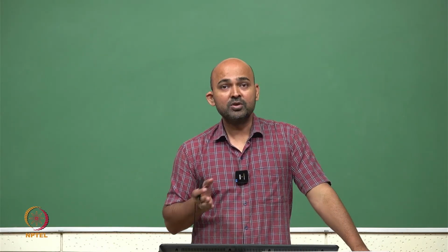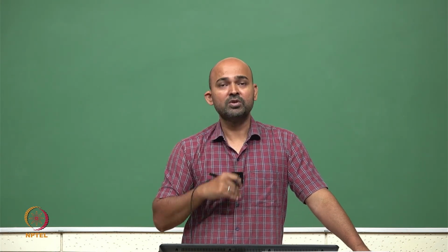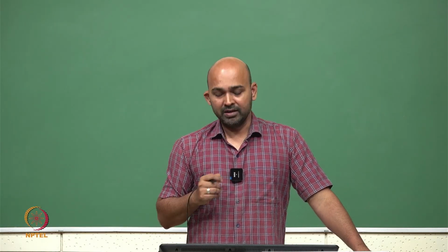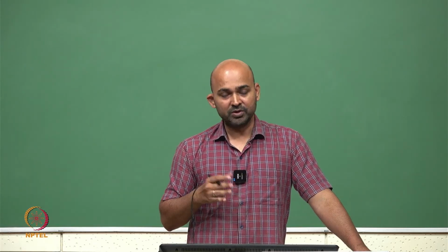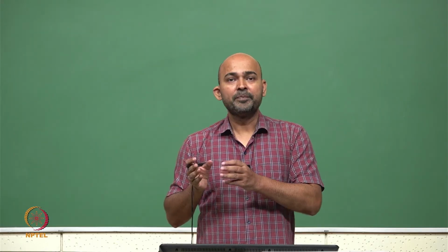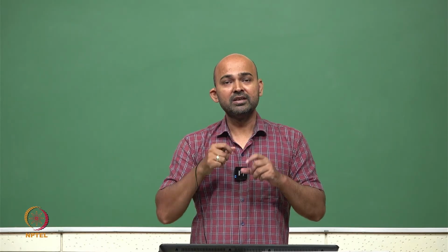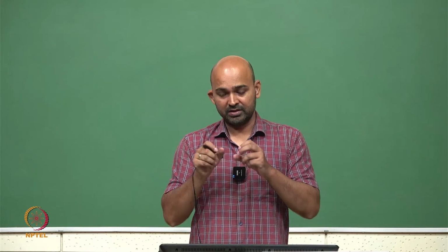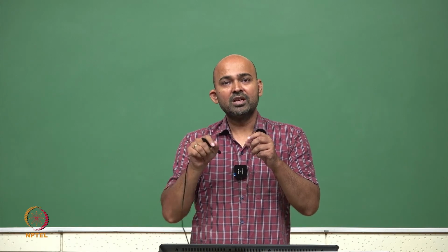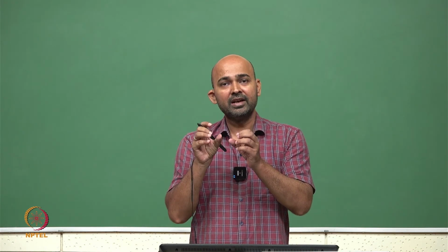However, this microstrip is exposed to the environment, at least half of the substrate is exposed, and if there is noise in the environment, that can directly couple to our microstrip. So, this is on the disadvantage side. The strip line, however, is not so easy to fabricate, because in the middle layer we need to fabricate this strip line, and the whole of the surroundings is made using dielectric material.